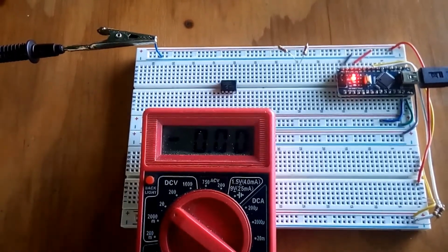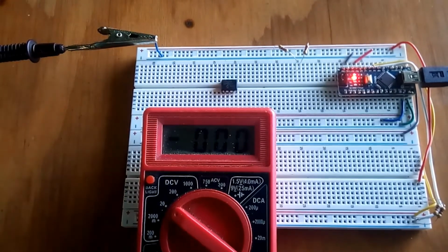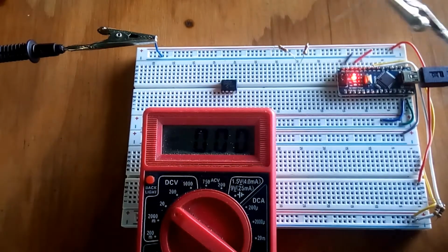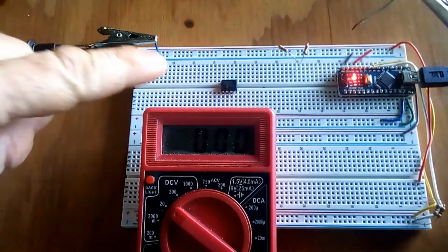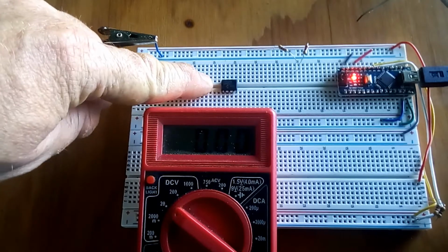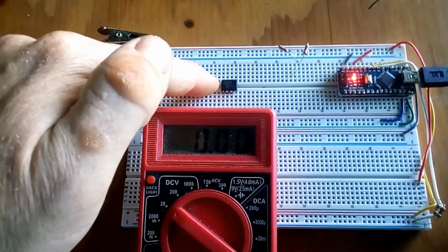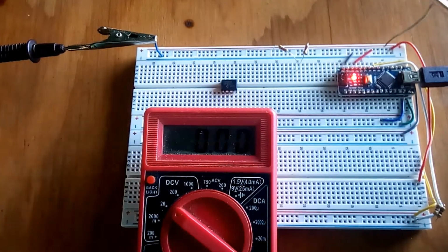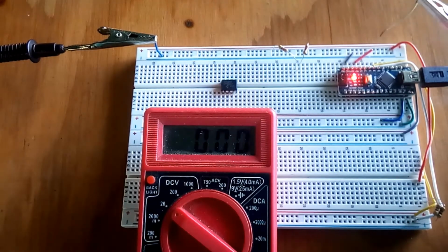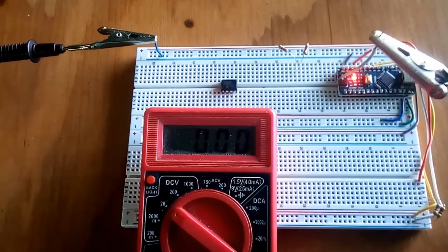So this video doesn't seem to be taking too long, so I thought I'd work this in here. This is something that's happened a lot in the playlist and not been discussed with hooking up the circuits. But the chip is going to operate off 3.3 volts. Somewhere between 2.6 and 4.1 volts is the range we can use with this chip. But the Arduino, while it does have a 3.3 volt supply that we can send to a power rail, the pins for controlling things all operate with 5 volts. So I need to cut some of that voltage out.